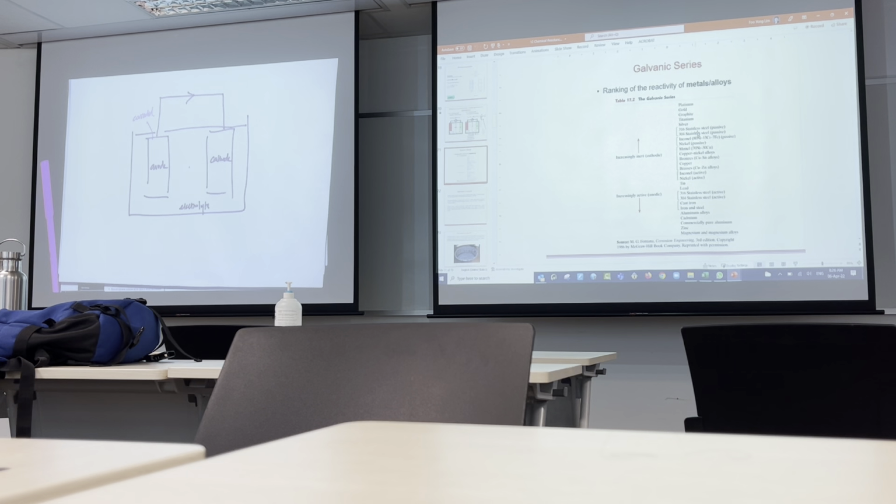That's the oxidation layer. A very simple example is aluminium. If you cut a fresh piece, it's always very, very shiny. But the aluminium that you see is actually very dull. It has oxidized already. It has an aluminium oxide, and that's why it doesn't corrode as easily. So it's another one that is passive. And in fact, a lot of people will want to protect the aluminium by going through a process called anodizing. Have you ever heard of this word?